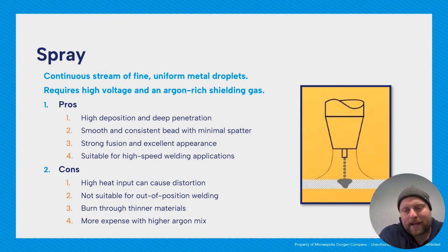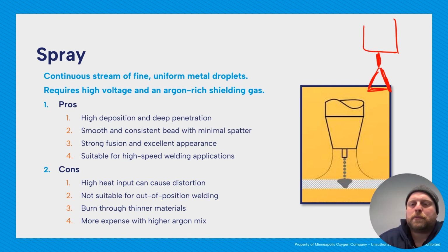So I just really want to make sure that's clear, because I see that as a mistake people make all the time. They'll stay there in spray. And so I'll look, and if they have a 75-25 cylinder set up, you're not doing spray. Spray is really cool though, I think, because when you do it, if this is our nozzle and there's our filler, it comes out in a little fan shape almost. And it is kind of like spray painting. You're just kind of spraying it into the joint.